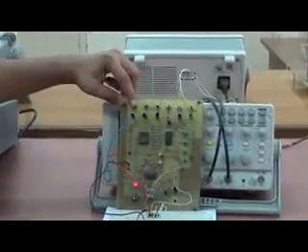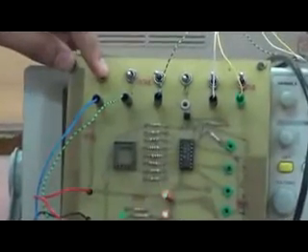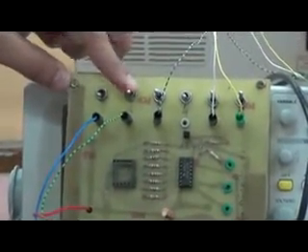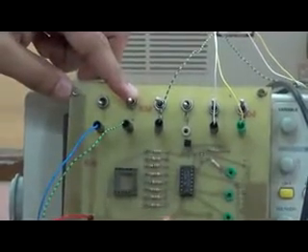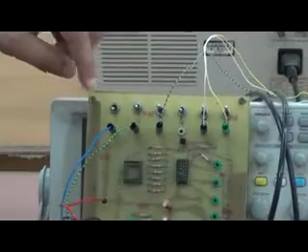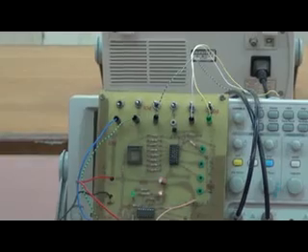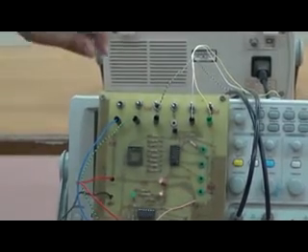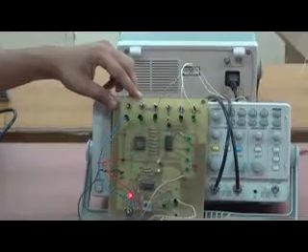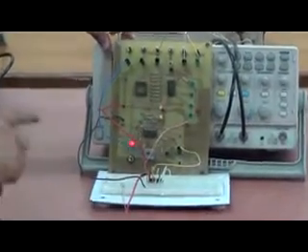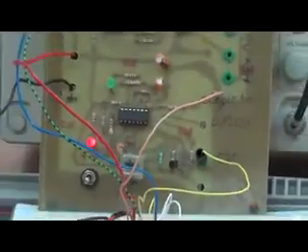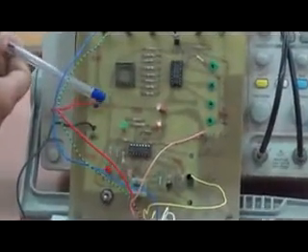The first switch is connected with the J input of this IC, and this switch is connected with the K input of this IC, and we have connected a clock from the digital test board to this IC and given a power supply from the power supply generator, that is of 5 volt. Currently this red LED is showing the clock variations, that is the positive and negative cycle of the clock. The output will be verified on this green LED on this digital test board.